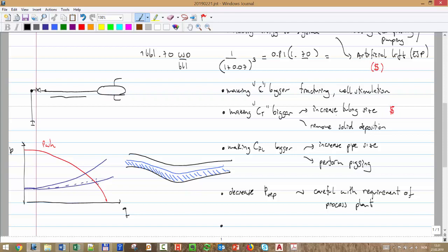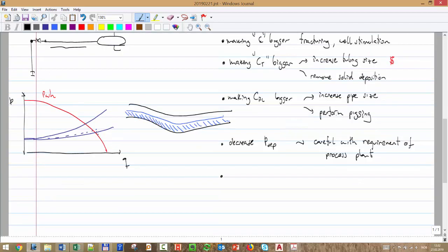Okay, then we can also try to slow down the decline in reservoir pressure, right? That's the other node that we have. So how do we do that? Water injection, pressure support. Yeah, water injection, gas, maybe we don't do it, but let's use a pressure support mechanism, if we can. If we have an oil, we can just simply inject gas or water. If we use gas, it's slightly more complicated, but we want to simply support reservoir pressure, so the decline won't be so abrupt.